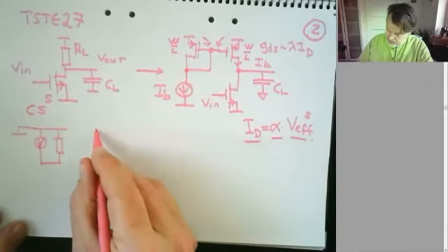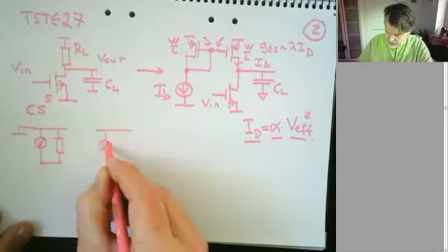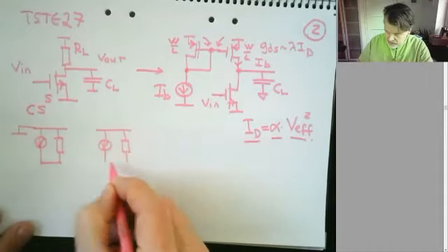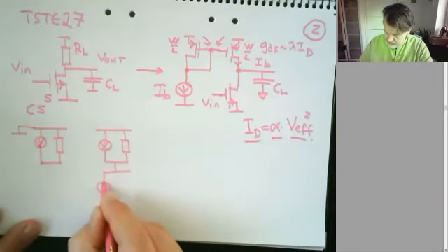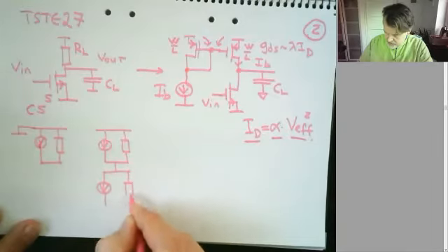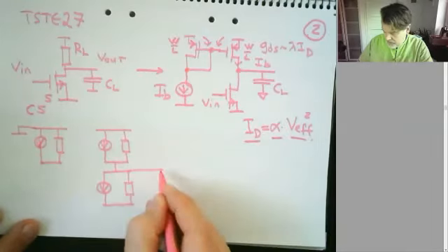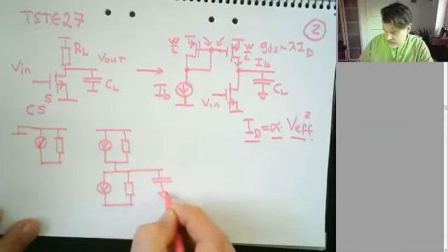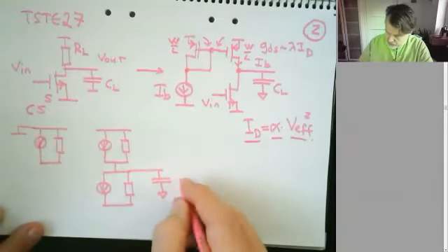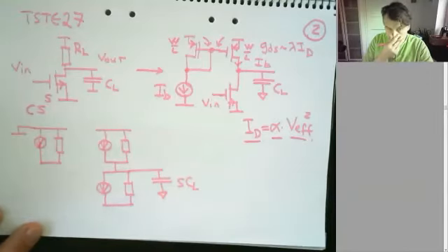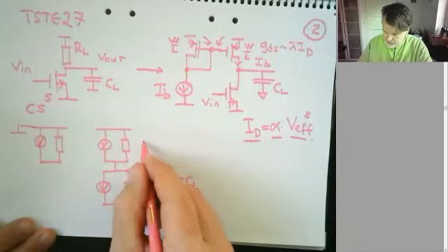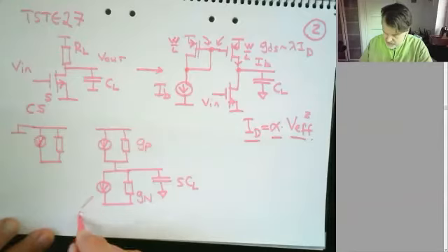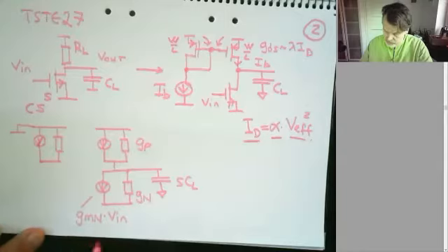And then I have my other transistor, like a current source and an output impedance, connected to my drive transistor, and CL, which I could replace with a box, but let's write sCL. That's my admittance for that. And this is now GN, this is GP. That's GMN times Vin in my small signal schematic.